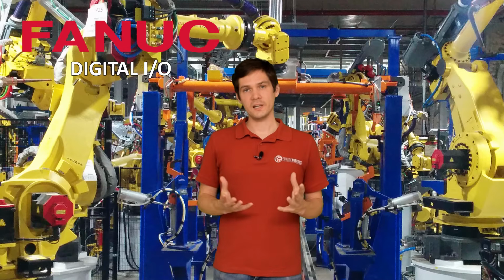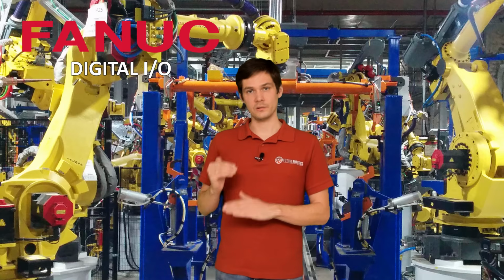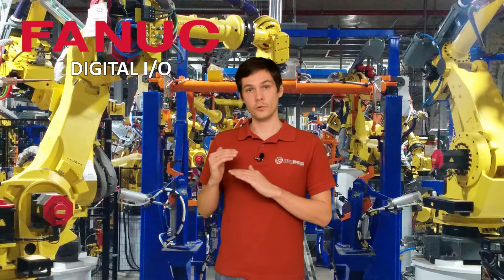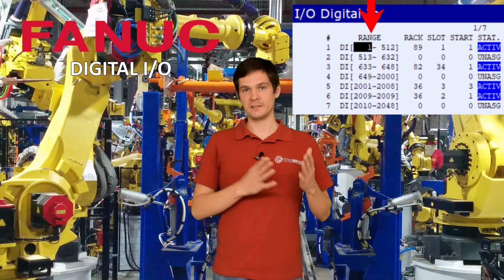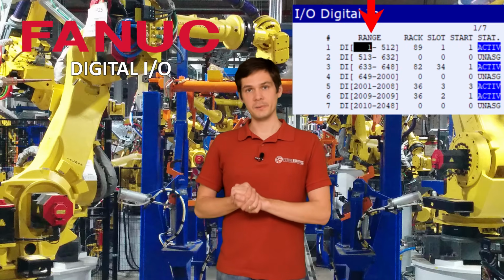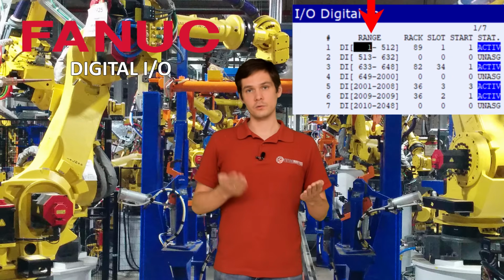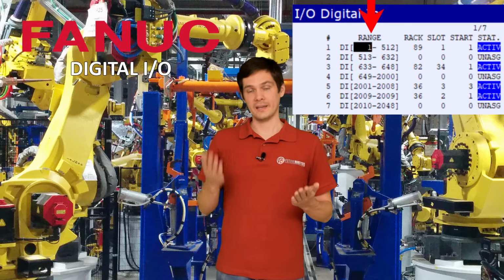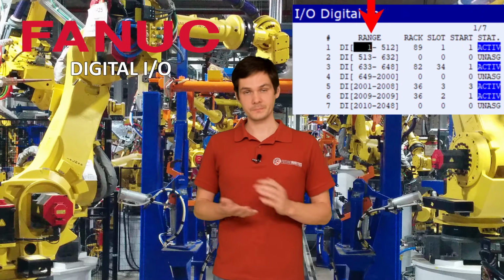Most likely, whoever programmed the robot, like most of the robots that will be programmed, the IOs are going to be split into a few ranges. So what is a range? A range is basically the number of the IOs that you're using. For example, let's take the PLC. In most cases, all of the robots are going to have a range from 1 to 512. And that's your range to communicate with the PLC.